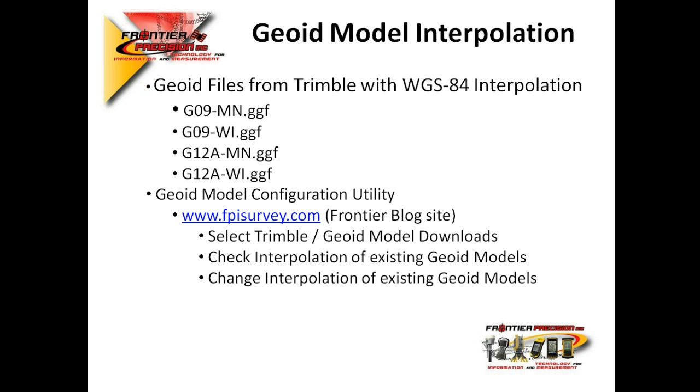You can even do it to your Geoid models in Trimble Business Center, or if you have your controller connected, you can even route the software to view the Geoid model right on your controller and re-interpolate it. When you re-interpolate a Geoid model, you need to make sure that it's not being used by your software, however. So make sure when you're running this utility that Trimble Access is closed down on your controller, and or Trimble Business Center is closed down, so that it doesn't give you a warning message that the Geoid model is being used and it won't let you interpolate it.